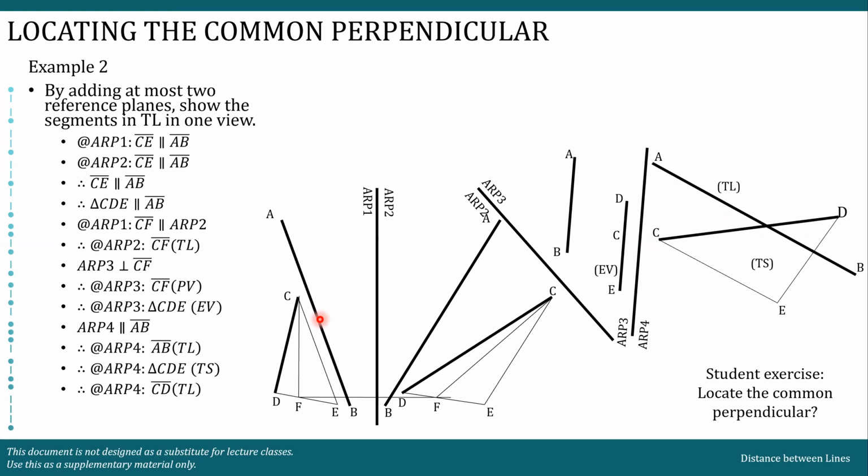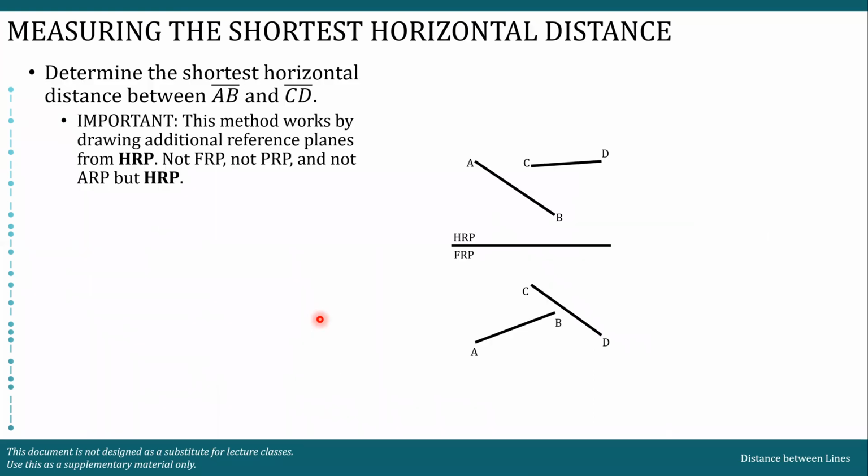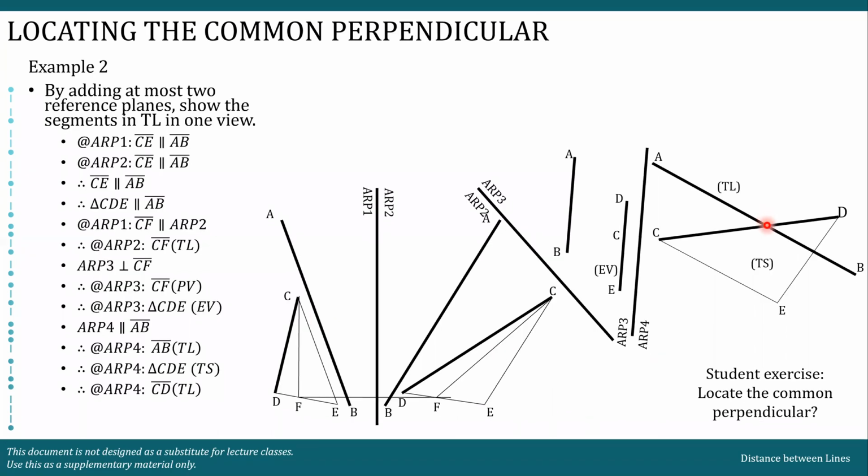Again, the question would be, saan kayo magme-measure ng length? Kapag ito yung method na ginamit ninyo, saang reference plane kayo magme-measure ng length? Well, the answer is just look for the view wherein the common perpendicular appears in true length. And since point view siya dito, it goes to say na kapag pinroject ko yung point view across the reference plane, it will appear as true length. So it will become true length here. Then you should measure the distance between the lines or the segments in this view. Okay.